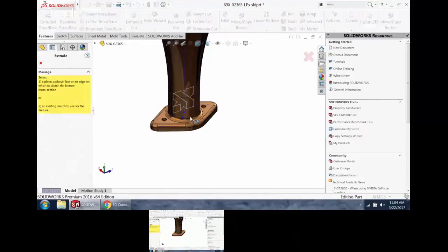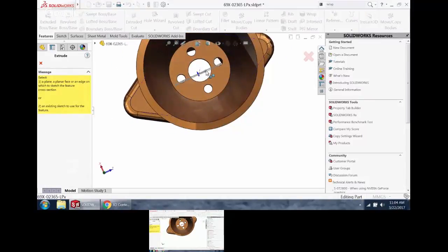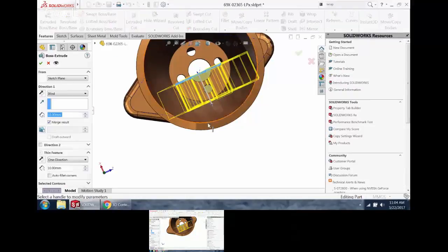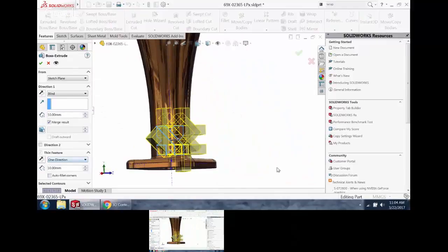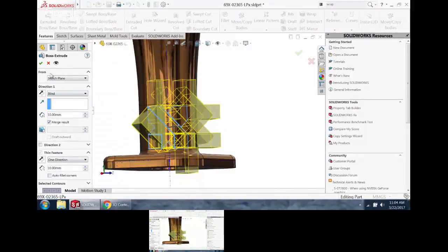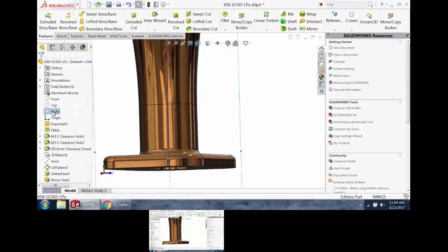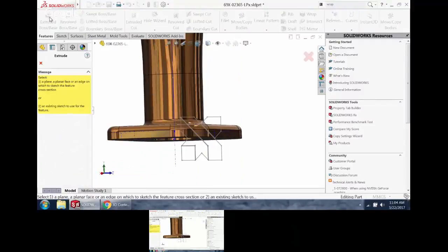If I want to make sure something can be used for a feature, really the first thing I'll do is pick that sketch and try to extrude it. If it can extrude, it'll be fine, but it's doing a thin extrude, which means that when I did that click and drag, I didn't put the points back together. So no problem. What I'm going to do, still got the same thing copied and pasted to my clipboard.